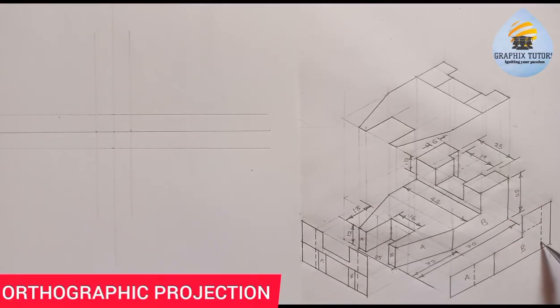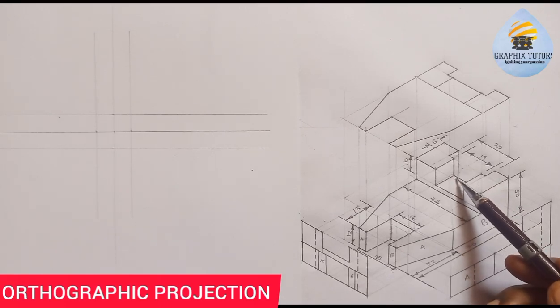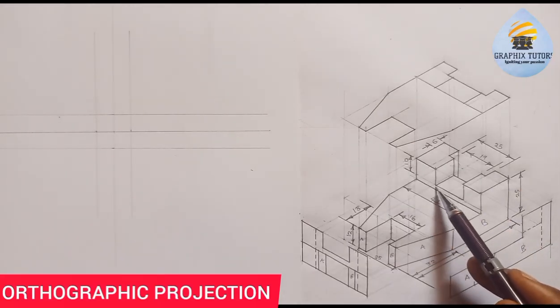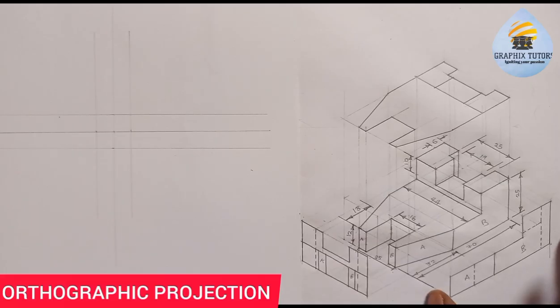So this hidden line you're seeing here is that when you're looking at it from here, you cannot see this side here, right? So that's why we're using a hidden line to denote that there's something in this figure that we cannot see. Then this hidden line you're seeing here is this line that is here. You cannot see it from here. You see that here is plain. So to show that there's a hidden feature here, we use what they call a hidden line. So this is what you are going to place here.